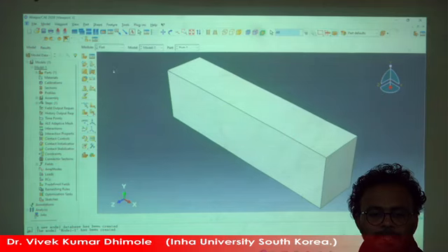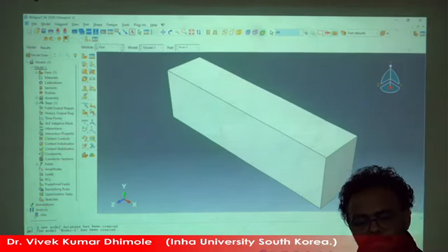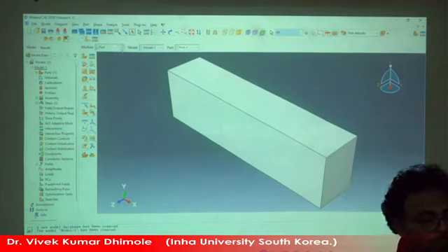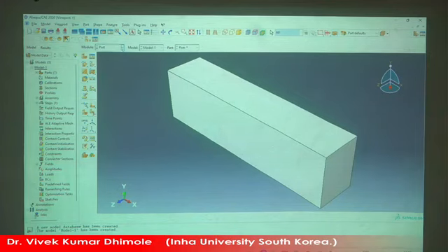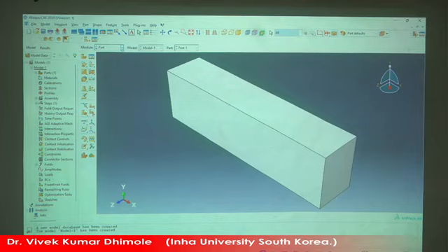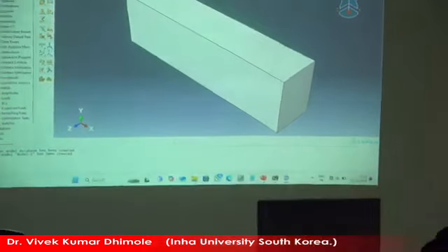This is just created, right? So now I think I created it very long. Also we have to understand unit consistency here, because in Abaqus you do not define the unit system, right? So you have to understand the unit consistency. If the dimension is mm, the result will be in megapascal, right? If the dimension is meter, the result will be in Newton. You have to understand the unit consistency system. Ton, Newton, ton, megapascal, mm, something like that, right? Kilogram, Newton, meter. Okay, this is the unit consistency system.